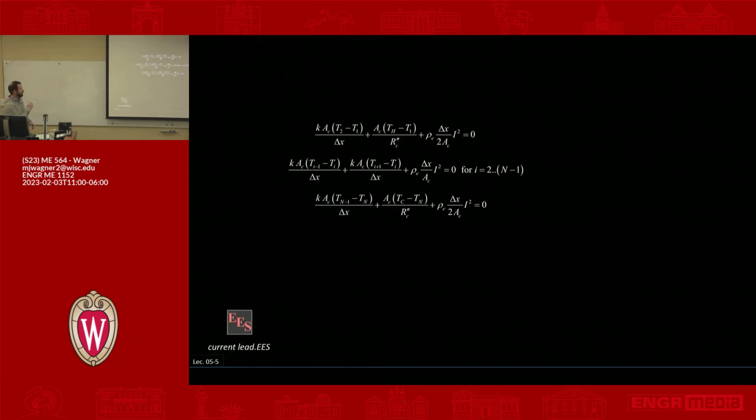All right. So here's our system of equations, right? We can synthesize this into a set of equations, write it succinctly. We have our three energy terms. They're equal to 0. It's because of energy balance. But you'll notice, like if I went through this and I had drawn the arrows a different way, like I had some Q dots going out or in, it actually shouldn't matter, right? You should still get this set of equations because it's just a matter of having a minus sign in front of temperatures that are flipped, right? So ultimately, you should end up with this no matter how you approach it, as long as you're careful in that process.